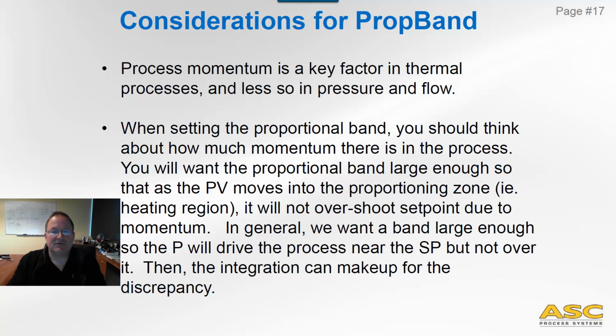So some considerations for the proportional band. The process momentum: depending on what we're controlling, the process will either have momentum or won't have momentum. Process momentum is a key factor in thermal processes and less so in pressure and flow. So thermal processes tend to have momentum. If you apply heat and then you turn off heat, the process keeps driving up because you have a lot of thermal momentum within the system.